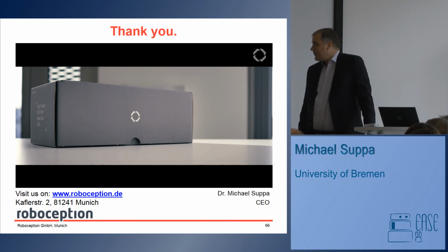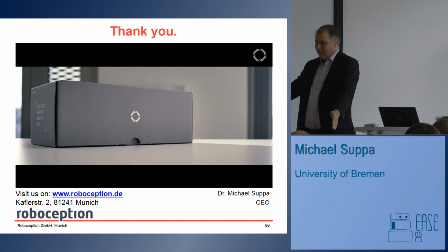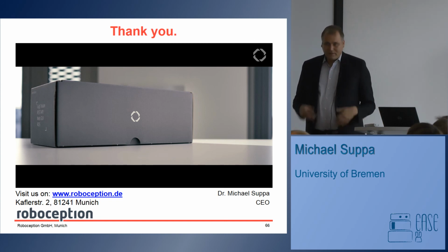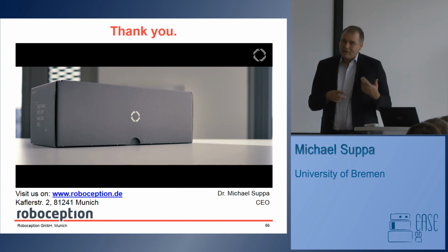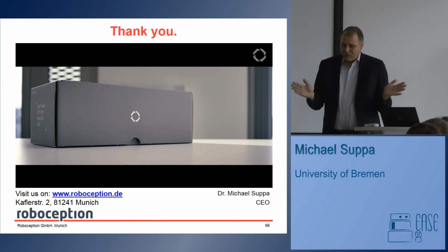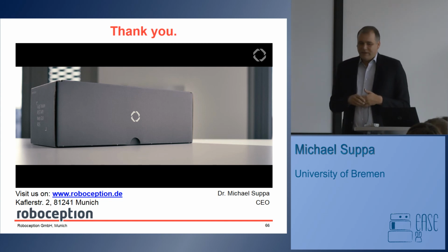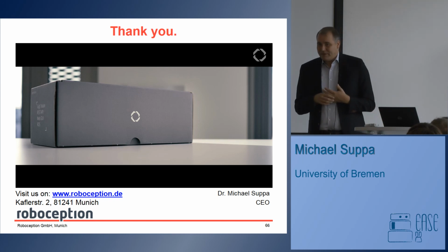So we went to that solution, this 1.3 megapixel CMOS fixed focus, because our task is that within the range of 2 meters, the maximum thing we want to detect is an area of a Euro pallet or something like this. That was the design criteria behind that system. If you go for any other camera design, let's say more of a fisheye view, it always comes at the cost of the calibration, and this really makes it problematic in some cases.